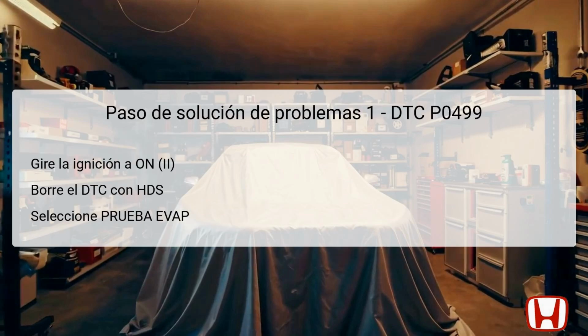The first troubleshooting step for DTC P0499 involves turning the ignition switch to the on position, which is essential for powering on the vehicle's electronic systems. Once the ignition is activated, use the Honda Diagnostic System, HDS, to clear any existing DTCs from the vehicle's memory.